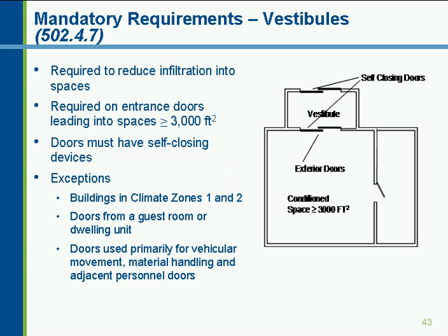One of the requirements that's been somewhat contentious since it came into the code is a requirement for a vestibule, and a lot of designers have actually gone into ASHRAE 90.1 to get out of the vestibule requirements for particular building stock. And that's worked well for them because they've complied with the envelope requirements for 90.1 and then the lighting and mechanical requirements in Chapter 5 of the IECC.